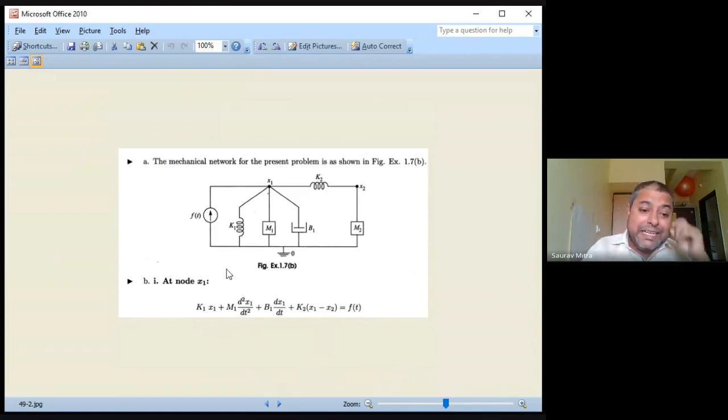Next you can take the Laplace transform, and you can find the relationship between x1, x2 and F(s). So there will be three main variables: F(s), X1(s) and X2(s). You cannot find X1(s) by F(s) or X2(s) by F(s) from there, because now F(s) is related to both x1 and x2. So the second equation will help you.